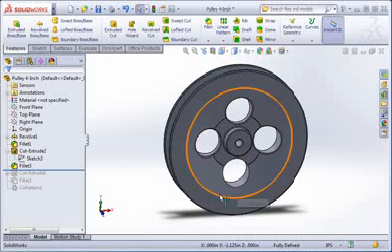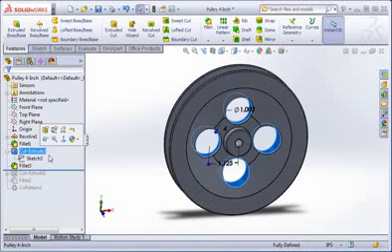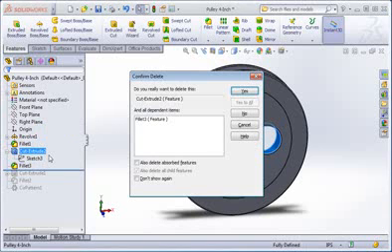You've learned the details of why you should not use sketch pattern commands, but for the rest of the course I'll limit my explanations to processes and commands you should use. That said, let's remove the holes constructed with the sketch pattern command and replace them with the holes constructed with the feature pattern command. Highlight Cut Extrude 2 and then type the delete key.